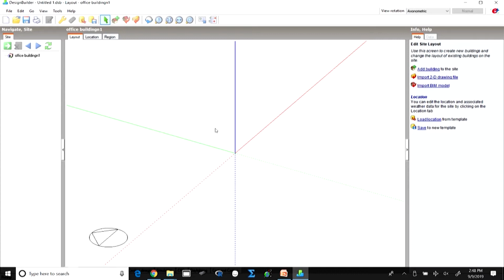Another important thing that we have to do is clean our DWG files, the drawing files, because a lot of details which are usually added in drawing files are not required for creating the geometries in whole building simulation tools. So, here the DXF should only have the basic information as far as walls and openings are concerned.